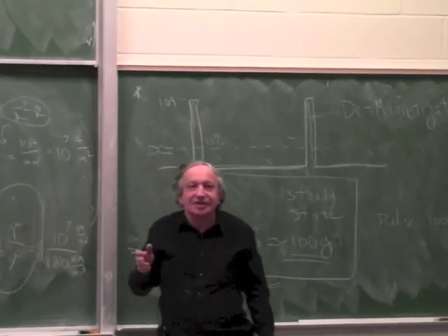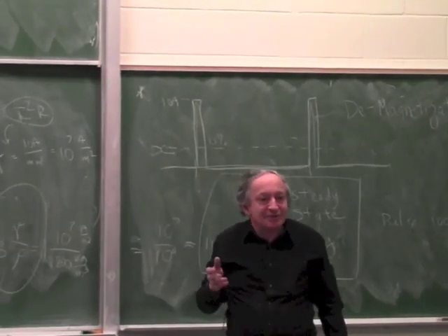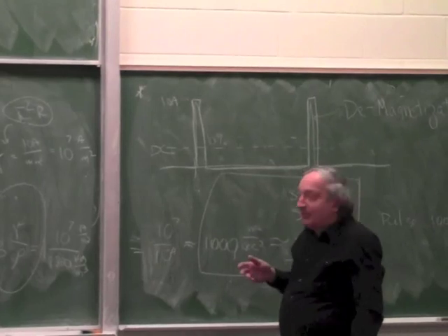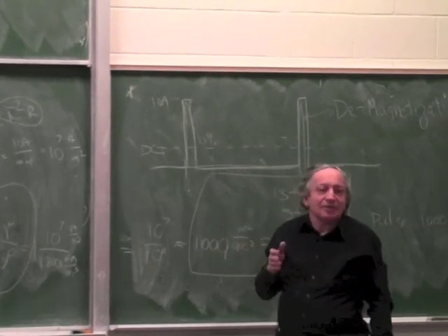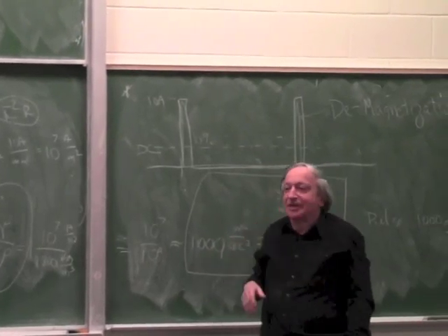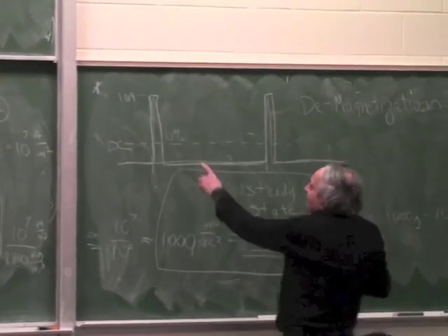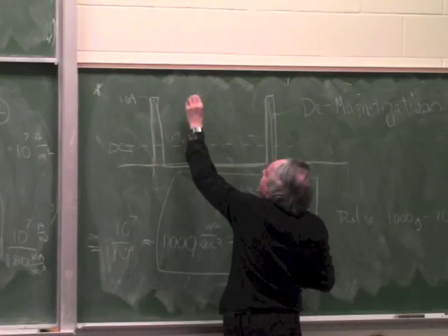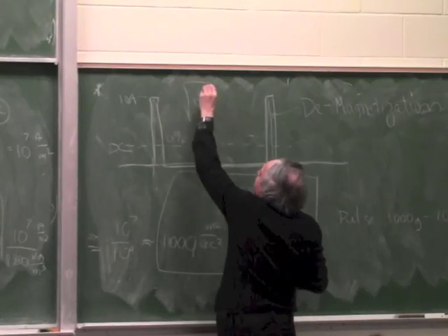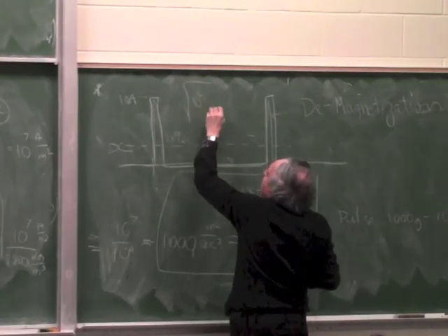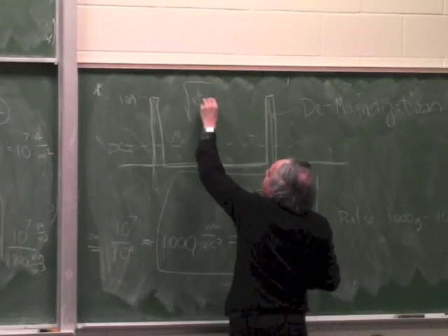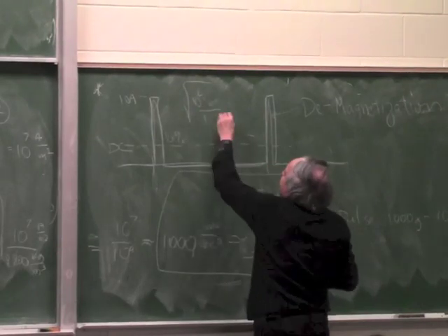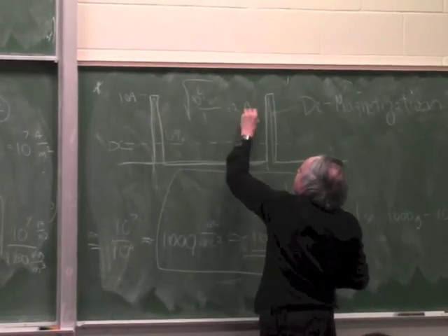So you can't take the average, you have to take the RMS value, right? Does everybody know what RMS value is? Yeah, I sure learned it enough times. So you have to take the square root of 10 squared times 0.1 divided by 1, and then you end up with 3 amps roughly.